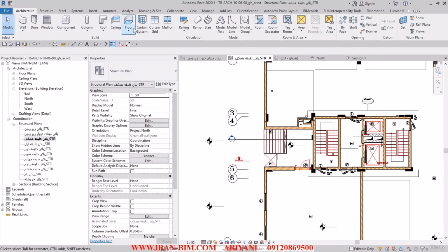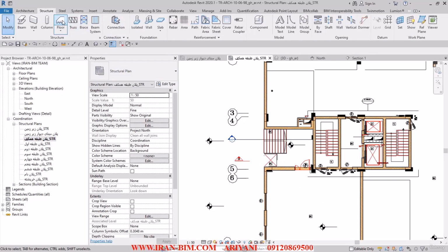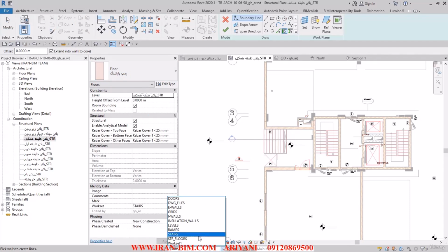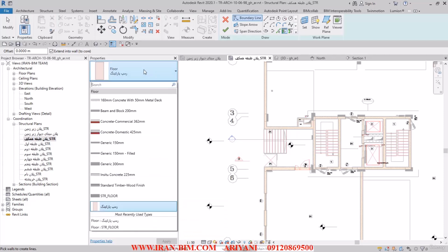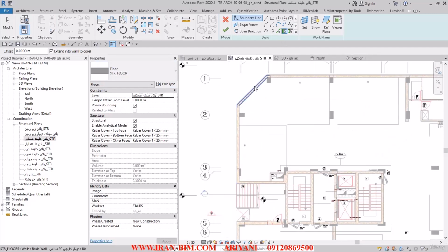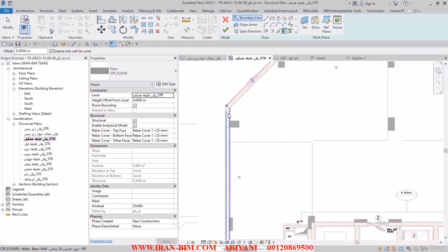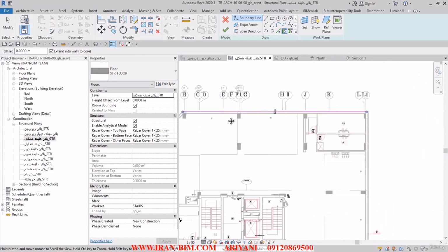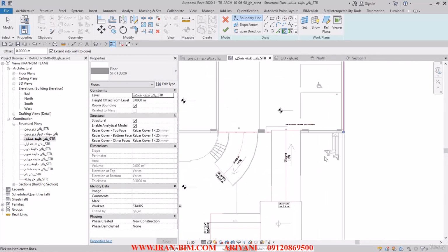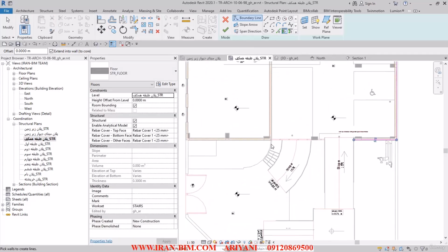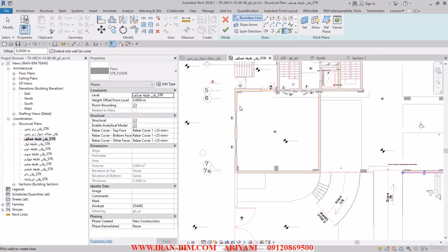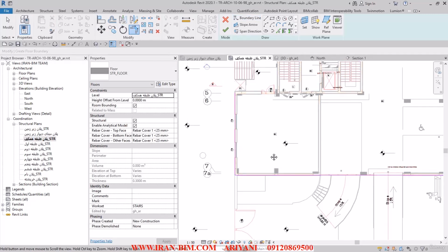So in this section, let's go down here and I put this on structural floors. We have STR floors right here. So I open this up here on the parking ramp and I pull it up to STR floor, and then the pick a wall tool, and all around the walls that we have here, we start the framework. So I put one here. Let's see, another one here, another one here, and using the trim a corner tool, I trim this one with